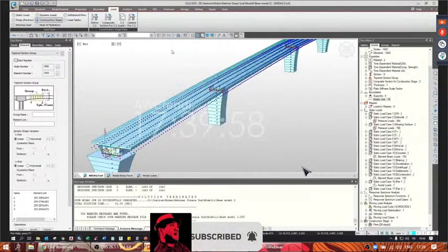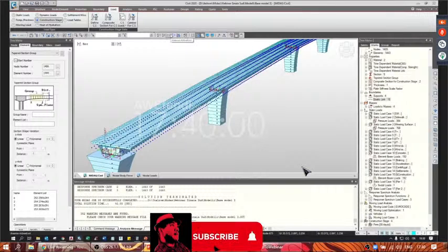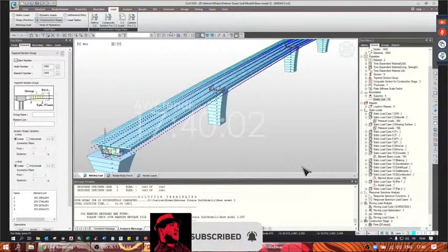Well, time-dependent effects have to be taken into account, especially for sections with parts in class 3 or 4, and for SLS checks. Since in these cases elastic analysis is required, the history of construction stages has an effect on final stresses. The time-dependent effects for the concrete can affect the deformations, like creep and shrinkage, and the resistance, with the increasing of compression strength in the days after casting. We can define the laws and define these phenomena in properties here.